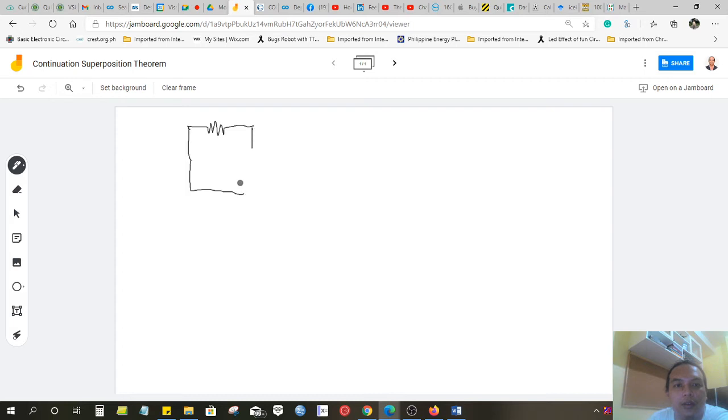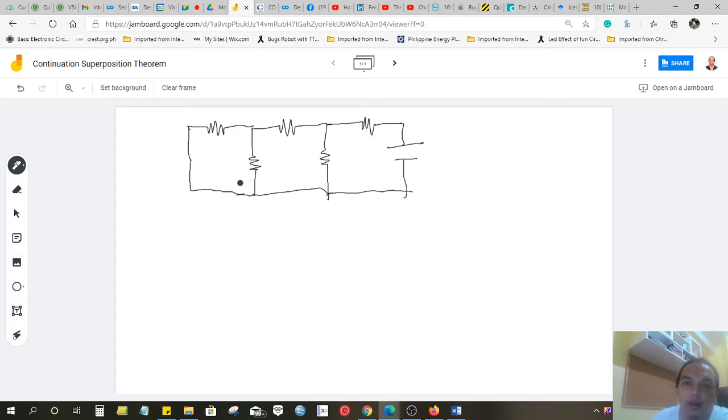That is our purpose in superposition. In the superposition theorem, we need to find the value of the currents of a certain load with respect to the independent sources. Our independent sources are 25 and 20 volts. So, we have 20 volts here. The same process: 3 ohm, 2 ohm, 1 ohm, 6 ohm, 8 ohm. Again, the source is short circuited and removed, so to complete the circuit, you put a wire.